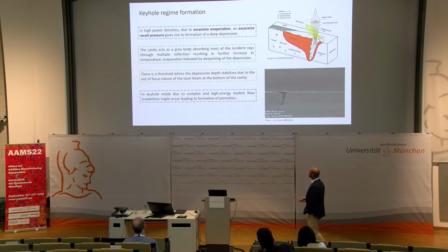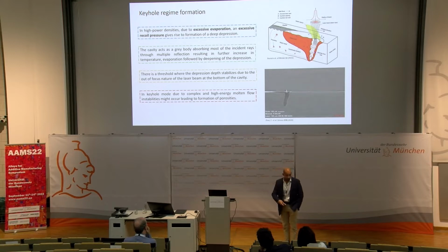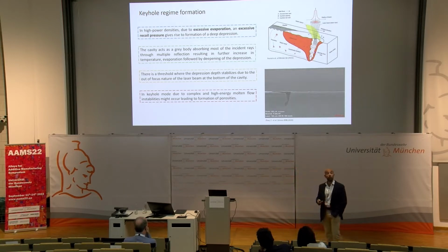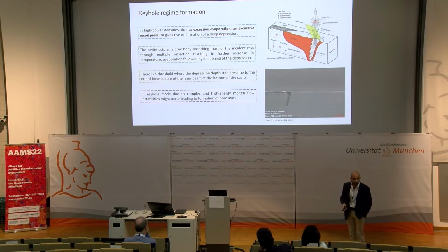In the keyhole mode, due to this complex and high-energy molten flow, there are instabilities, there are going to be collapses, there's going to be porosity formation, which are detrimental for the mechanical properties, and we would like to know if it happens, because it's going to happen.